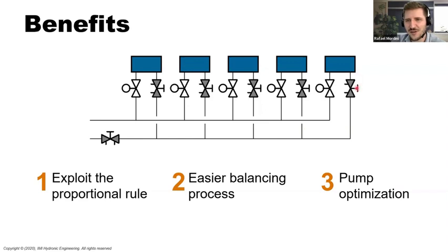And if you just close these valves and get the design flow rate, are you saving that much energy? You know, what you should do is balance between them and try to figure out the overflow that you might have on this branch. And you use this valve here to remove this overflow. So let's say this here is a small branch on a floor. Then you do this on the entire floor. And then you do this balancing within all the floors on a riser. And then we are going to balance the risers. At a certain moment, we'll have a main valve there that will be passing the flow rate of the entire pump.